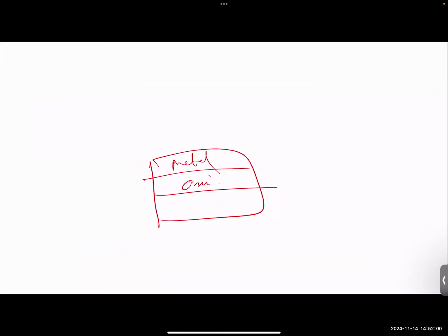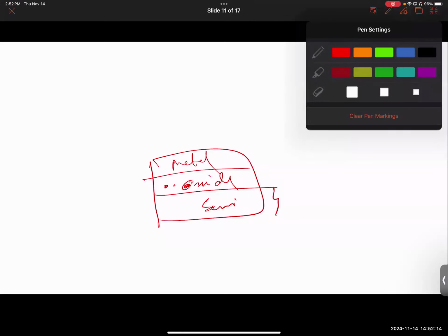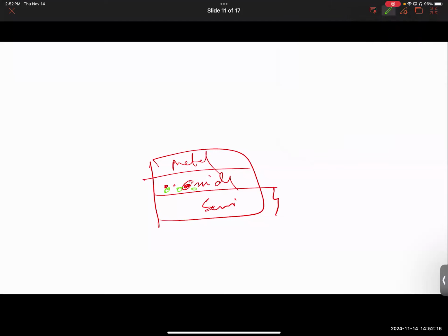So MOSFET is, you have a metal, you have an oxide, and you have a semiconductor. All interesting action will occur at the semiconductor layer. But oxide could also have some impact. Oxide can have fixed charges. I told you that before, but we didn't really discuss this to that degree. It could have fixed charges, basically stuck. What do I mean by fixed charges? They don't change based on the voltage. Doesn't matter what type of voltage you apply, these charges will always be the same.